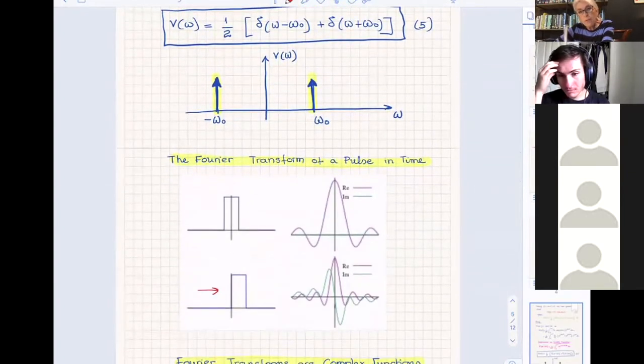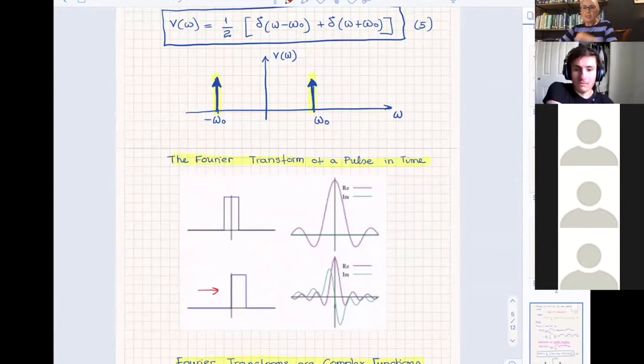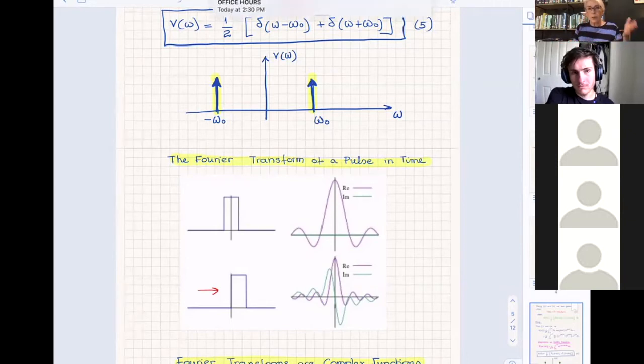Now, if you take the Fourier transform, as you know from phasors, a Fourier transform and a phasor are practically the same thing. The difference is that the Fourier transform is for a general function, and the name phasor goes only to a monochromatic function. So practically a phasor is nothing else than the Fourier transform of a monochromatic function, considering the counterclockwise kind of movement.